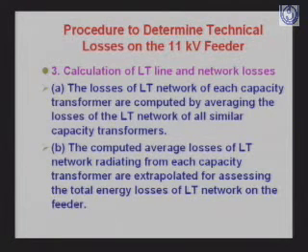To the best possible, we should try to assess technically. If we know the conductor's size, we know what the resistance is. Through kVA, as I said, we know to what extent the load is there. We should try to work out technically or use whatever software is available. This type of assessment is best avoided wherever it is possible.